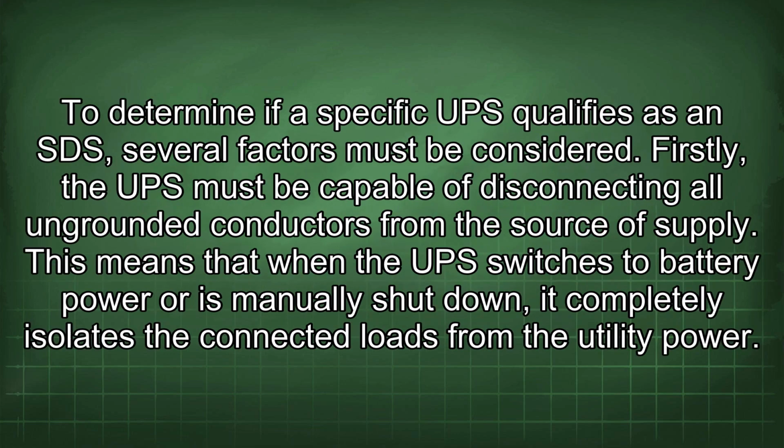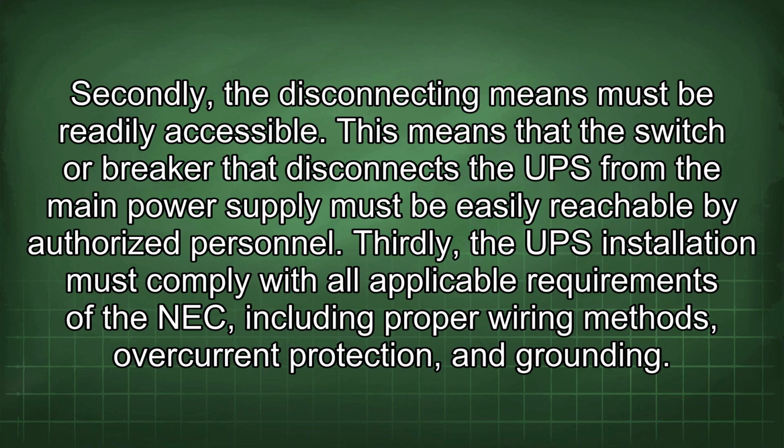To determine if a specific UPS qualifies as an SDS, several factors must be considered. Firstly, the UPS must be capable of disconnecting all ungrounded conductors from the source of supply. This means that when the UPS switches to battery power or is manually shut down, it completely isolates the connected loads from the utility power. Secondly, the disconnecting means must be readily accessible. This means that the switch or breaker that disconnects the UPS from the main power supply must be easily reachable by authorized personnel. Thirdly, the UPS installation must comply with all applicable requirements of the NEC, including proper wiring methods,